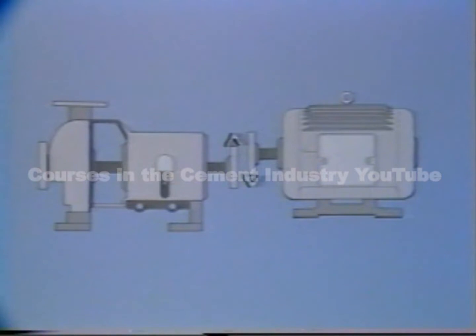We measure the offset between the outer diameters of the two coupling halves. In other words, these distances indicate how much too high the motor is. The same measurement can be used to determine horizontal or side-to-side offset.